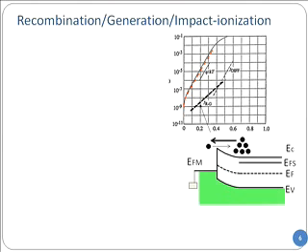Okay. Now, you can also do other things. Many times these devices might have a lot of traps between the metal and semiconductor side. And so in that case, what will you do? You will take exactly the same expression as for the p-n junction, and realize that dn/dt will be just like your p-n junction recombination, and you will integrate between 0 and W_n, because that's the depletion width, just like we did before. And you will do the recombination in the forward bias junction.